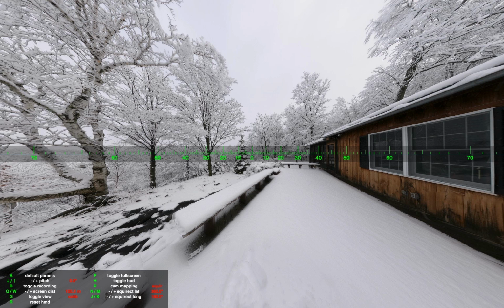This is the horizontal and the vertical field of view. As this is a full 360-degree panorama, I don't have to adjust these values because the default values already are okay. The default values are 360 for the horizontal axis and 180 for the vertical axis. You can think of this as spherical coordinates. So this is all I have to do.